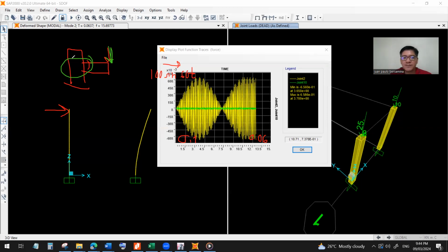Because, for example, you can vary the steel, like fy, or study a joint with no reinforcement. The cyclic response simulates the effect of an earthquake, because in an earthquake, your structure undergoes cyclic deformation. Remember, the moment diagram is at its maximum at the joint.